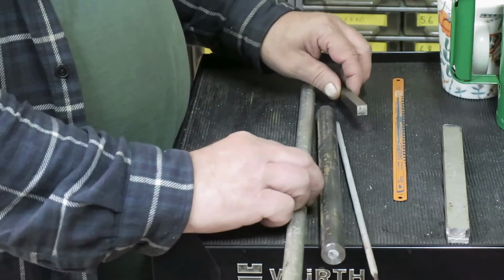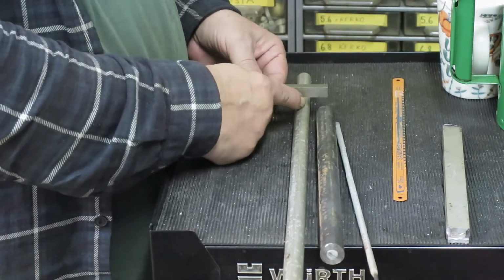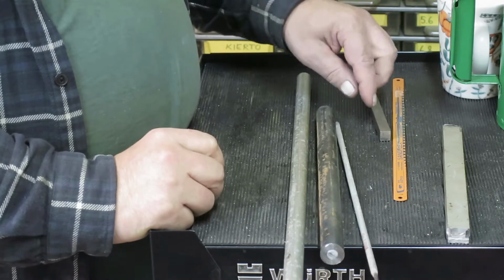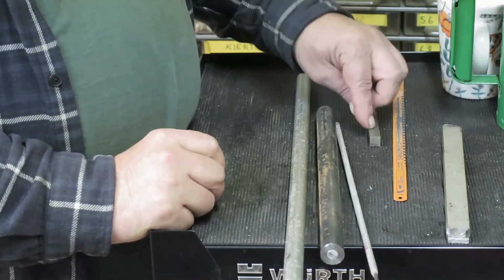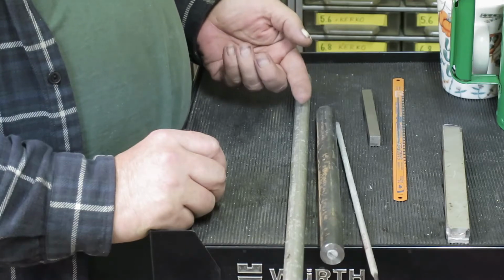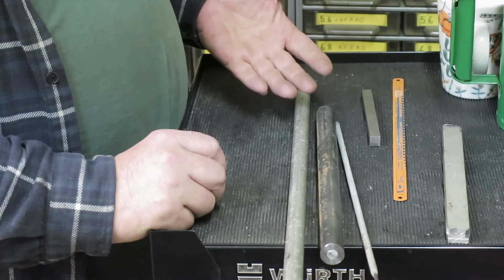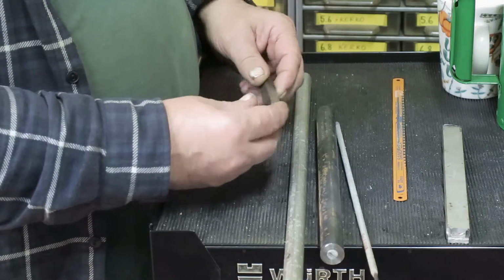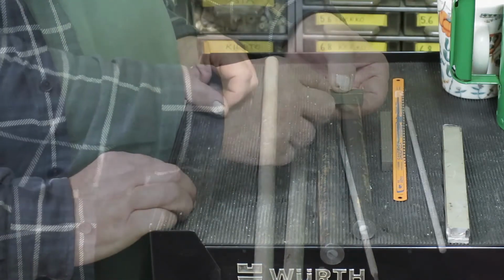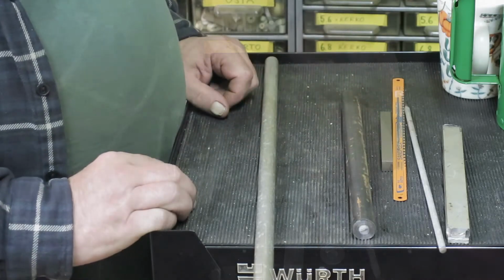And what I'm using as a bearing between these two materials is actually a ball bearing. I will make a dent into this one, and then we will have a ball bearing there, and it should hold itself in place. And then when we have a flexure here, I think we will meet in the lathe.